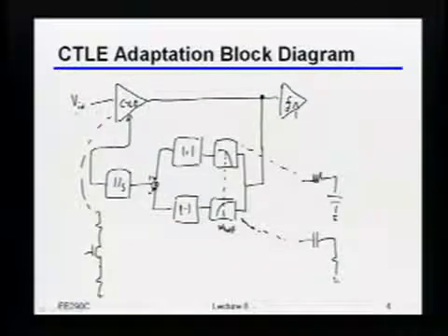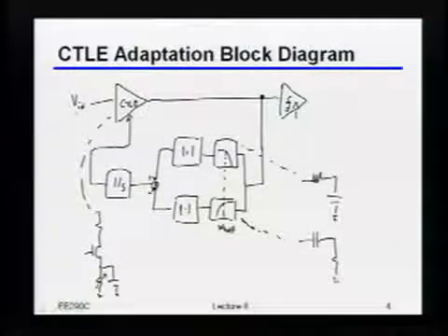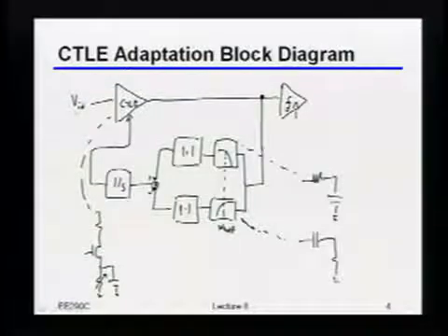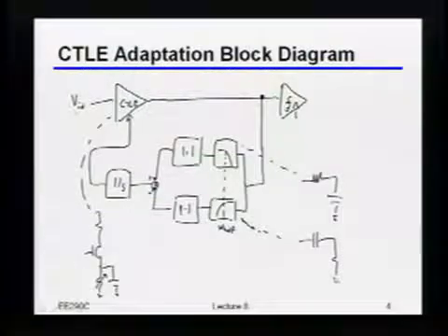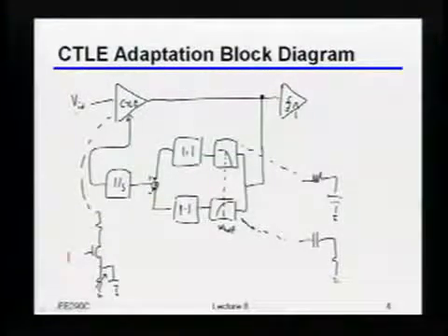The only thing you really need to tune is actually that resistance there, right? Because by tuning that resistance, you're changing both the peaking and the 0 location. Okay? Yeah? Is there a significant error by making that second filter high pass instead of band pass? Oh, okay. So in reality, even this filter will end up being band pass.